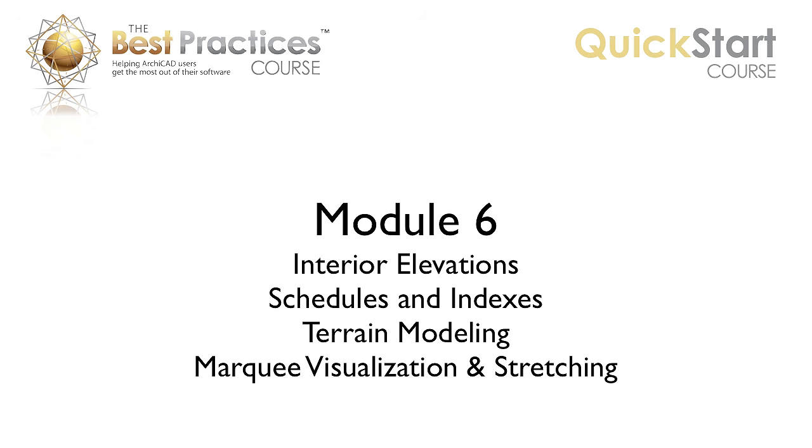In Module 6, we'll look at interior elevations, schedules, and indexes, which all are different ways of looking at the information in your model and allow you to prepare drawings and reports that you can place on your sheets. We'll take a look at terrain modeling with flat elements using the slab tool and more complex shapes using the mesh tool. Finally, we'll take a look at the marquee tool, which can be used for visualization and for editing and stretching by defining areas that you want to look at or modify.